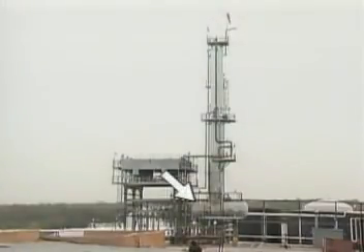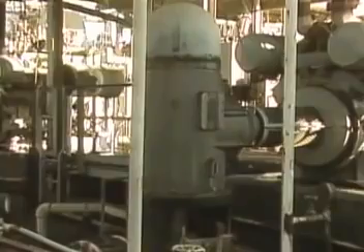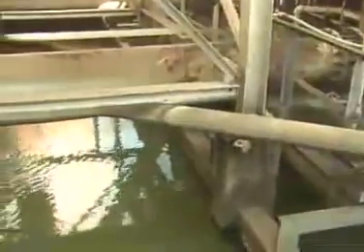During operation, motor-driven fans blow air around tubes in the condenser. Vapors from the tower flow through the tubes. The air absorbs heat from the vapors, causing them to condense into a liquid. The liquid or distillate then collects in a receiver. Water can also be used as a cooling medium. The water in a water-cooled condenser has the same basic function as the air in a fin fan condenser.